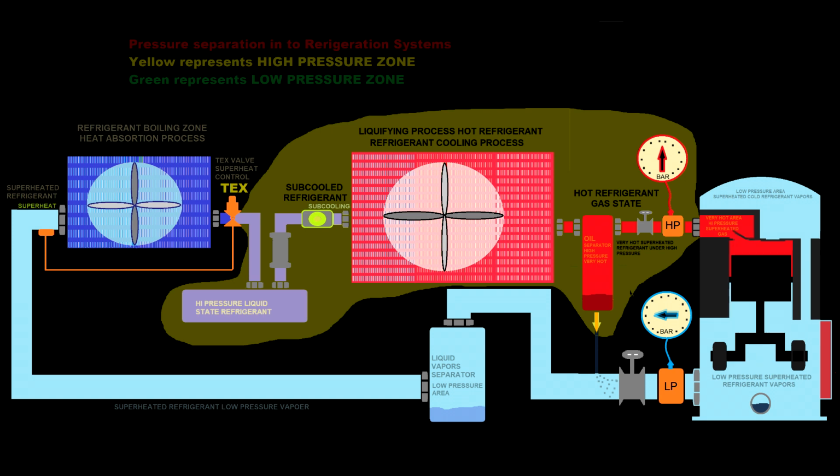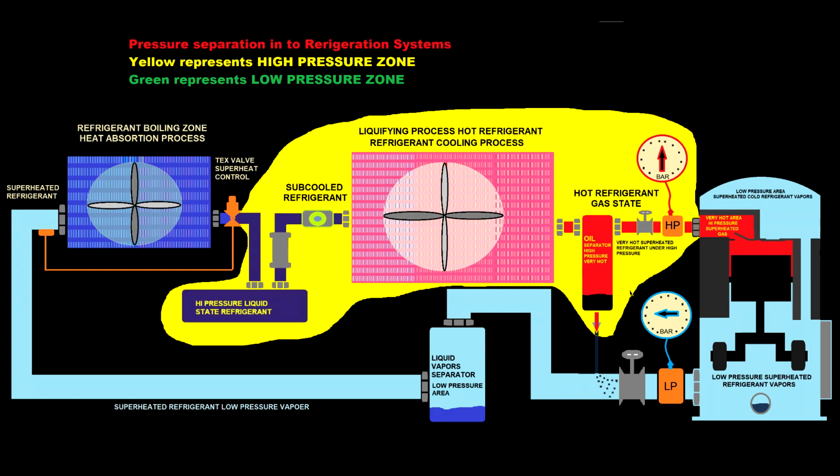Sometimes you have to check your refrigerant if you're not familiar with the job, because many technicians have been there before you, and as companies starve of money, some engineers, companies or customers will only tell you, don't do the vacuum, don't reclaim the refrigerant, just top up the refrigerant. And we all know that by topping up the refrigerant, we might end up with a different type of refrigerant, because when refrigerant leaks, it loses its properties.